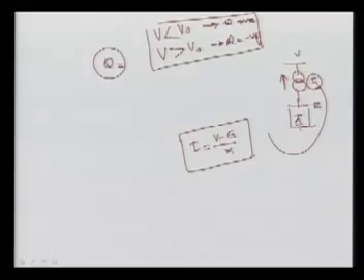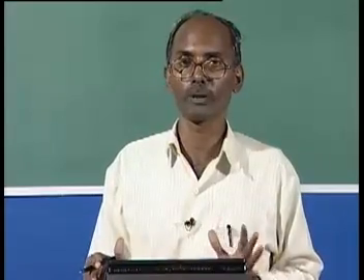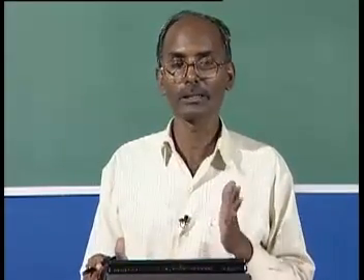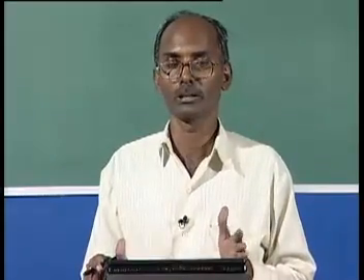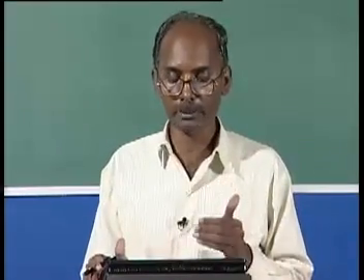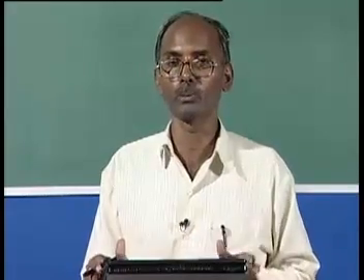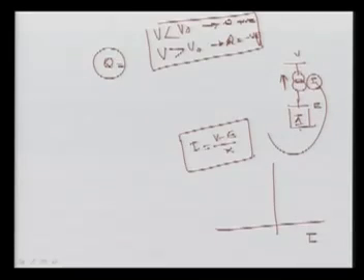So I can now recap with lecture number 9 and 10. Here I just discussed the FACTS controllers, only the shunt type, because the shunt type is very simple, and it is used for reactive power support, and along with that it will improve the dynamic performance. Here we saw the slope characteristic. Sometimes people ask why, in this VI characteristic of the STATCOM or SVC, we do not go for zero slope. We always go for some slope, and at minimum we go for 2 to 5%.